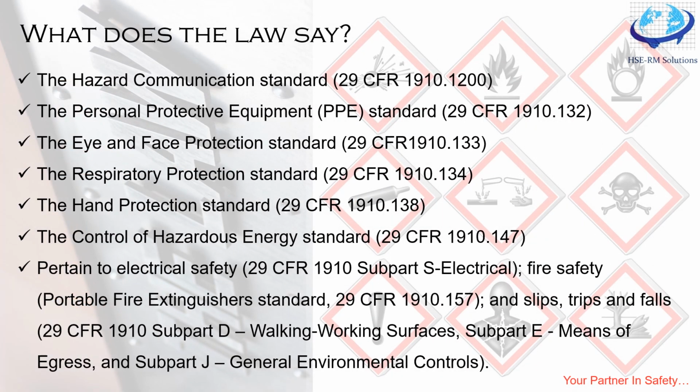What does it say? So what are the standards that we are talking of? Firstly, we are talking about the occupational exposure to hazardous chemicals in laboratories standard, that is 29 CFR 1910.1450. Now the other standard is the hazard communication standard, that is 29 CFR 1910.1200. The personal protective equipment (PPE) standard, that is 29 CFR 1910.132. The eye and face protection, 29 CFR 1910.133. The respiratory protection 134, the hand protection 138, and the control of hazardous energy, that is